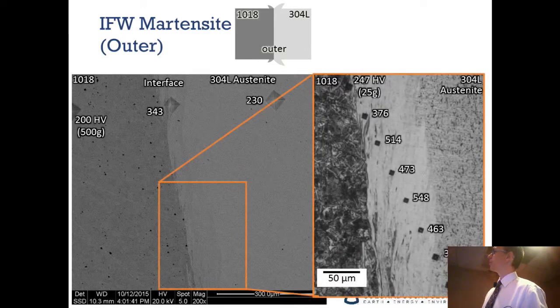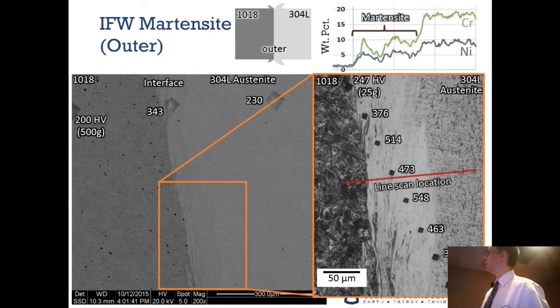However, at the outer edge of the friction weld, there's more mixing. You've got those two pieces closer to the periphery, there's more rotation, and there's going to be more heat and more mixing in the solid state weld. So there's more of this martensite, and you can see it has an interesting interspersed layer morphology to it. There's more of a transition zone, but again, it's interspersed layers.